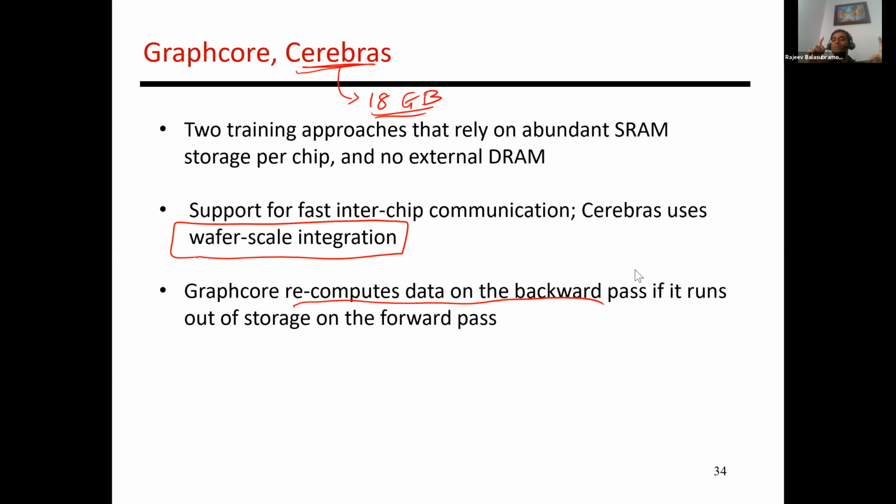If you have a 128 by 128 crossbar, it's going to take 2^14 steps to program each cell individually, and each cell itself can take many hundreds of nanoseconds. So using analog for training in general is not a great idea. There are people that have made assumptions about better cells and have shown that it's possible, but we may not see those cells in a commercial setting for a really long time. I digress from your original question, but hopefully that gives you a little bit of insight.